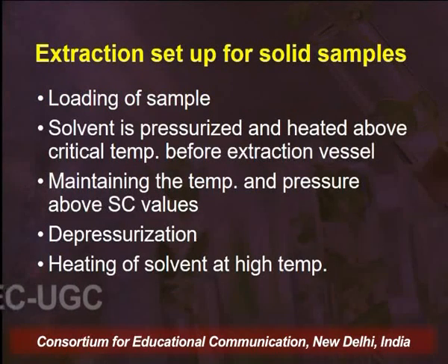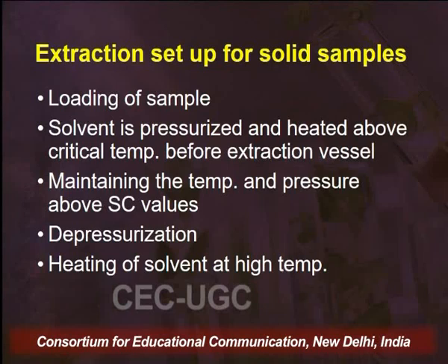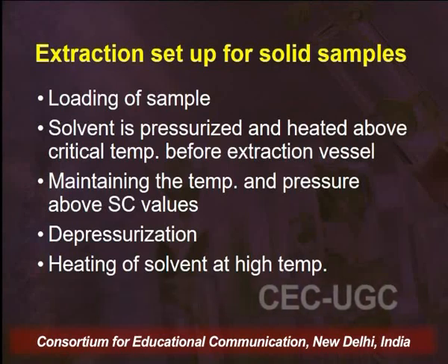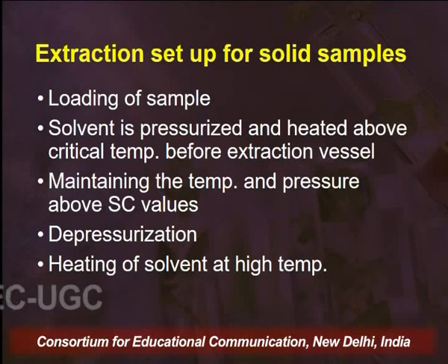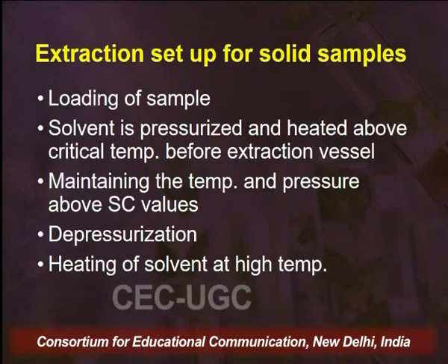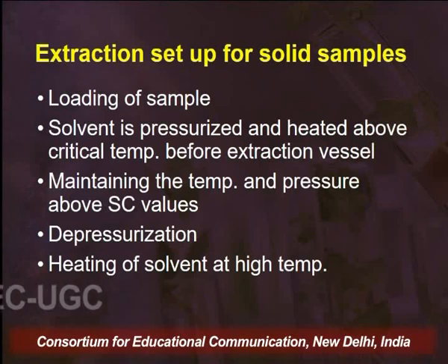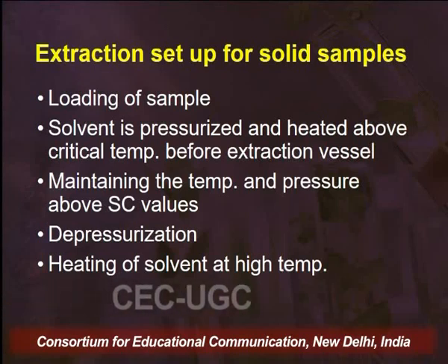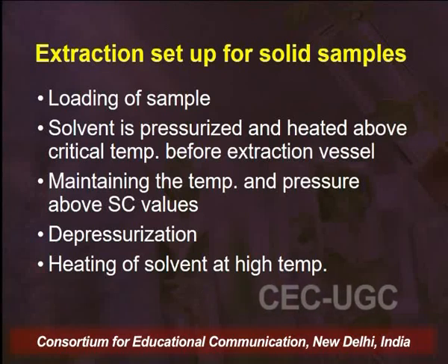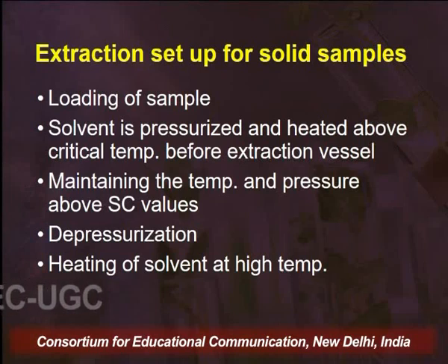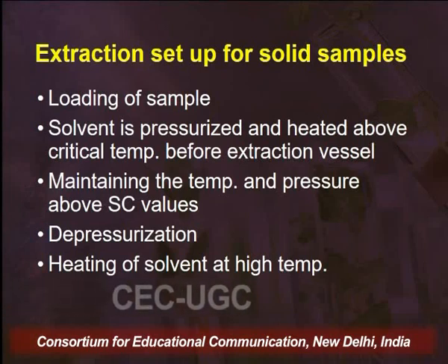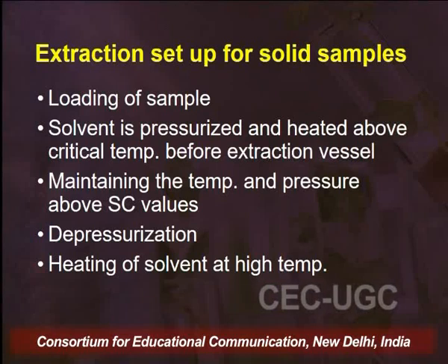Now we move on to the extraction setup for solid samples. There are different steps involved for solid samples. Once the sample is loaded in the extraction vessel, the second step involves the introduction of solvent into the extraction chamber. Before we introduce the solvent into the extraction chamber, the solvent has to be maintained at the pressure and temperature conditions that are required in the extraction vessel.